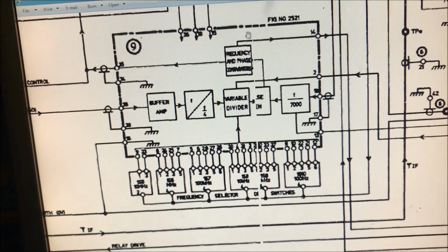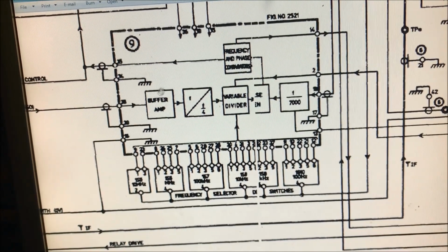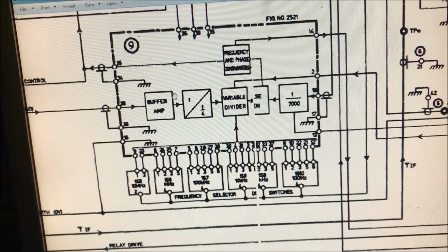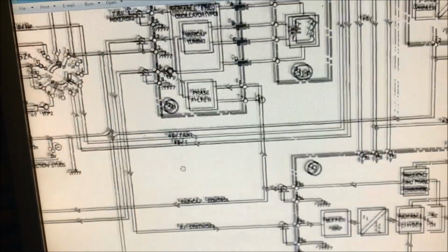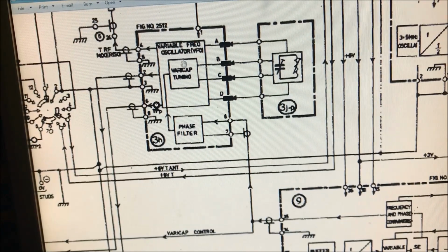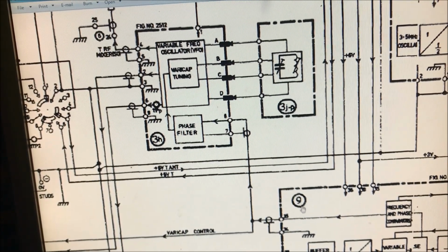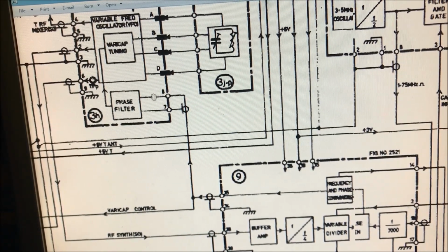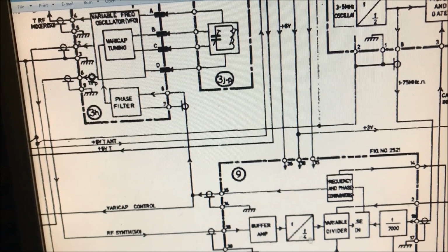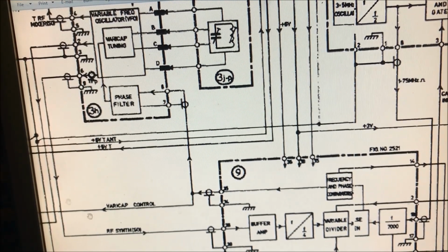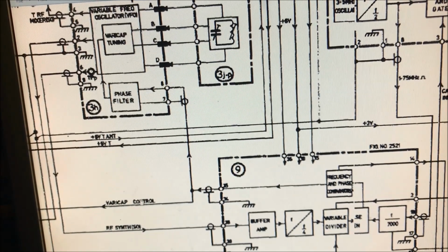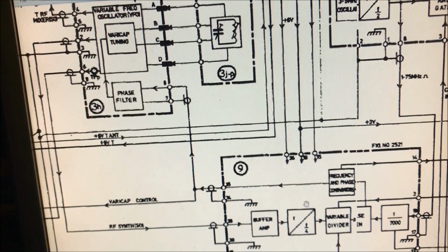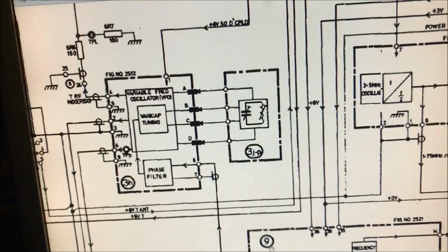Okay, so yeah. So what we're going to actually do is we're going to try and find out whether it's the synthesizer next that's causing the problem, or it's in fact up here in our 3H board, the variable frequency oscillator. So remember that these two are operating in a loop. The DC supplied, this generates the frequency, it's checked and varies the DC supply, and round it goes up and down, wobble. Okay, so what we're going to do now is we're going to look at how we're going to diagnose whether the problem is in the synthesizer or in the 3H board.